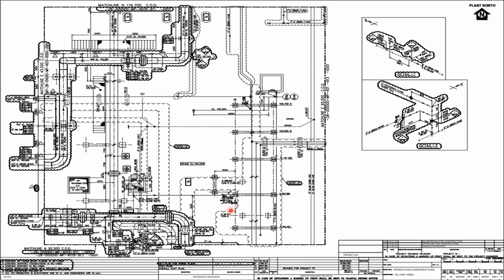See the layout how it is. There is so much information regarding the piping. You can also see the line number and the elevations and the support types, and there are cases where it is represented in isometric view also, because there are situations where, due to the congestion of the piping, you may not be able to represent both in plan or in elevation. So in those cases you will represent that in isometric view. The isometric view will exactly tell you what modification has been done. That is why we are delivering isometric drawings also. So this is the purpose of a GA. GA is actually delivered in order to address all the details of one particular area so that the readers can easily understand what modification has been done.